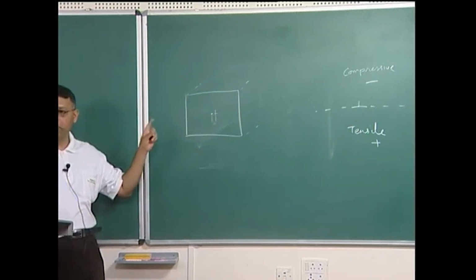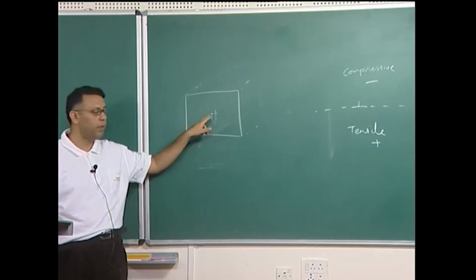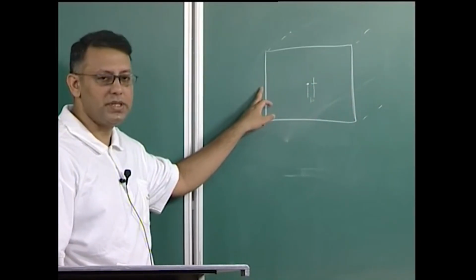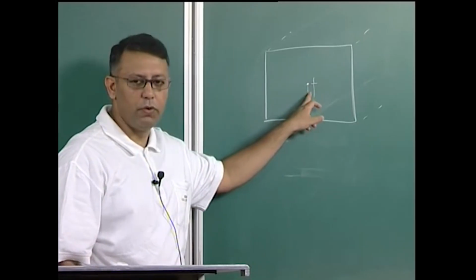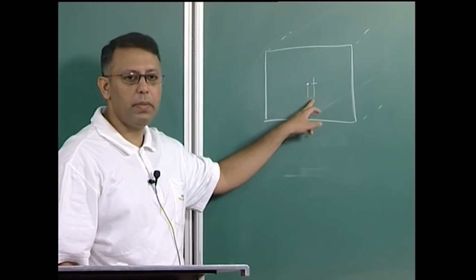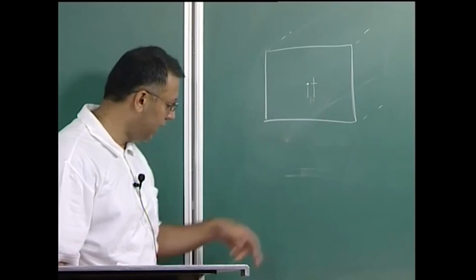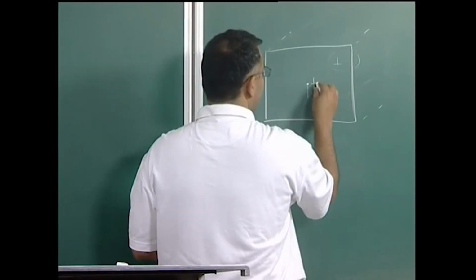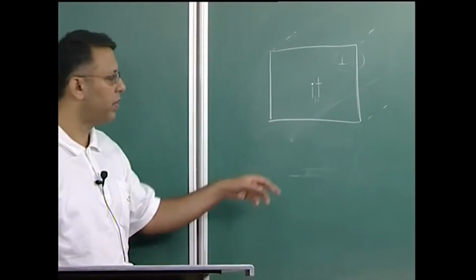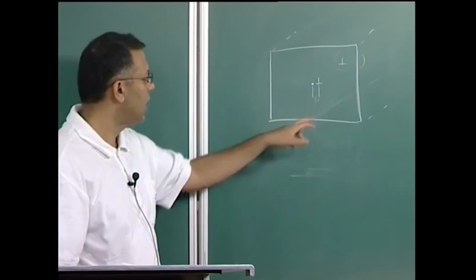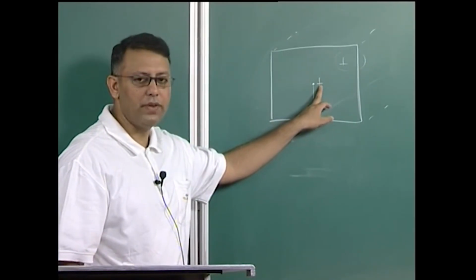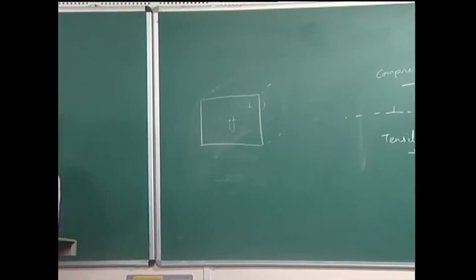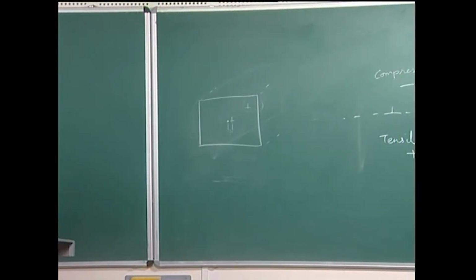Now you see the image force strength is going to be very, very weak, because this surface is not very different in distance from this surface. Even if this little weak force is larger than the Peierls stress, then all dislocations will leave; suppose you consider a dislocation here, obviously it is closer, it will leave. This is the worst case or near worst case scenario, because at the center a dislocation of course feels no force. If this dislocation can leave the crystal, then I assume that all the dislocations would have left the crystal, and this crystal will become spontaneously dislocation free.